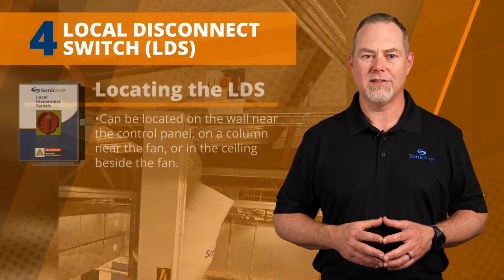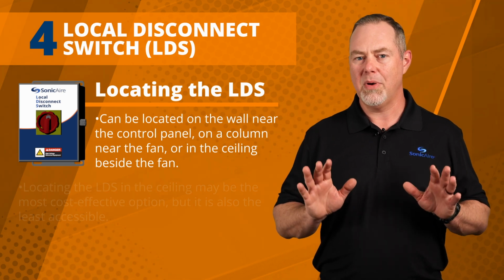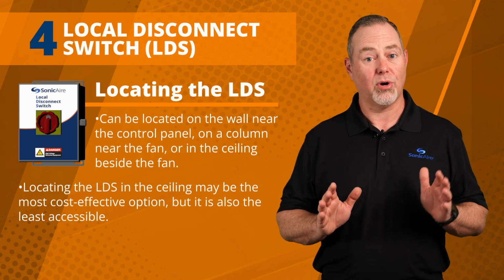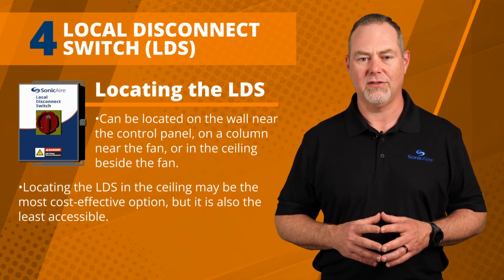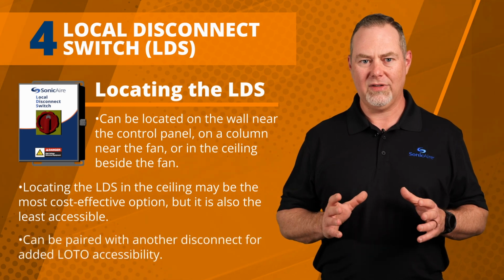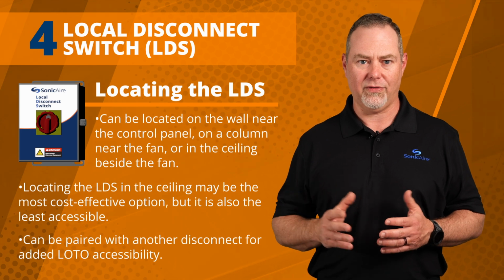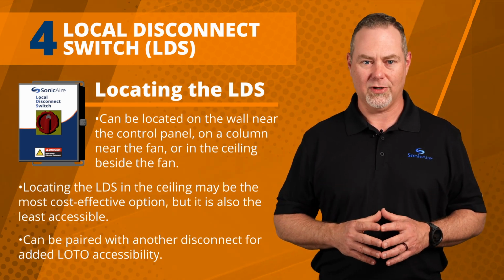Locating the LDS in the ceiling may be the most cost-effective installation option, but bear in mind that this is a resettable circuit protection device like a breaker in your house, and should it trip, you will have to go up to the ceiling to reset it. If you'd like to have the LDS wall-mounted but also want a lockout-tagout disconnect near the fan, we can do that by adding a simple disconnect switch near the fan as well.